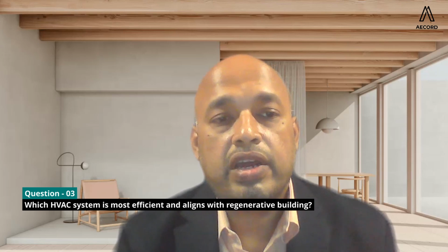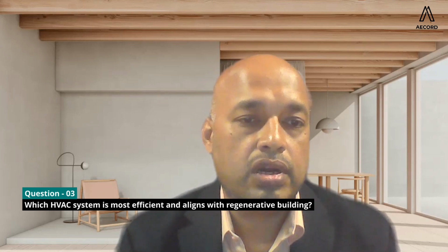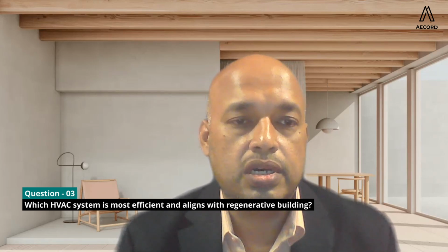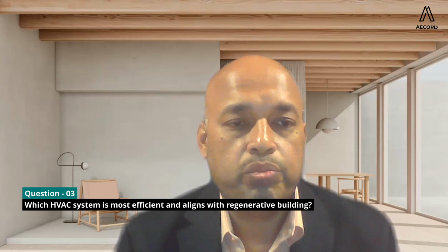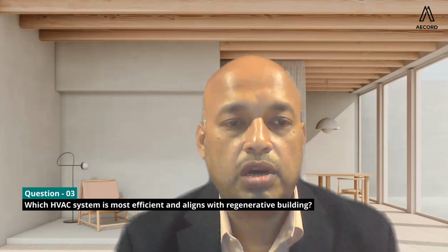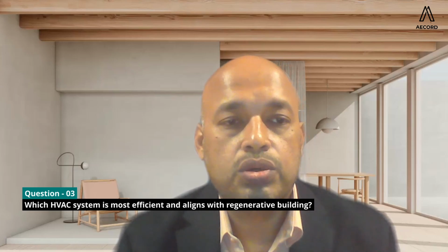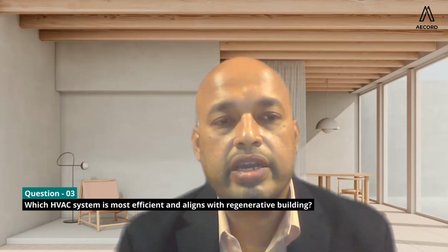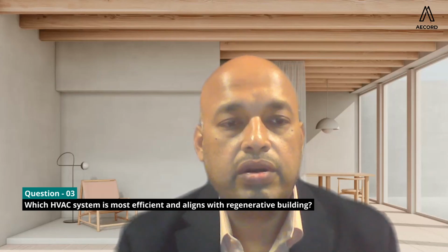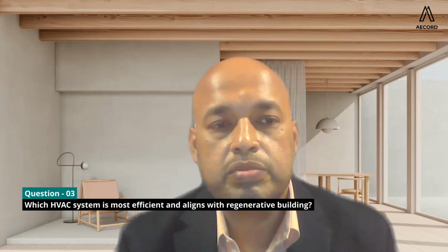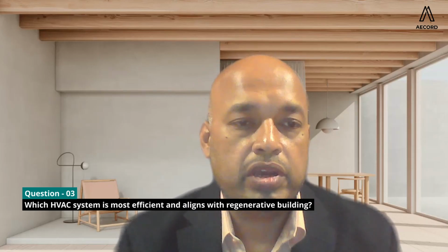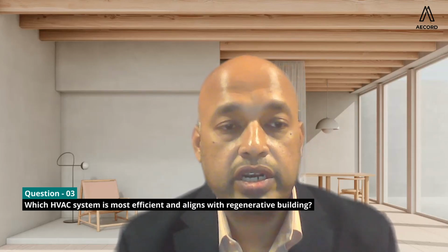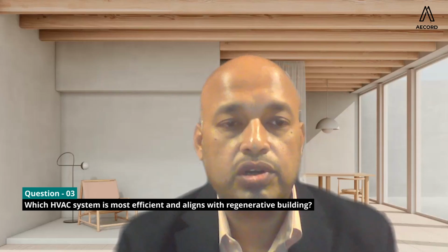But if you really require air conditioning, you need to go for VRF systems with high COPs, meaning coefficient of performance above 4.1. That is what I would recommend for residential, because concepts like chilled radiant cooling, which is appropriate for offices, you may not be able to install and operate in residential projects.